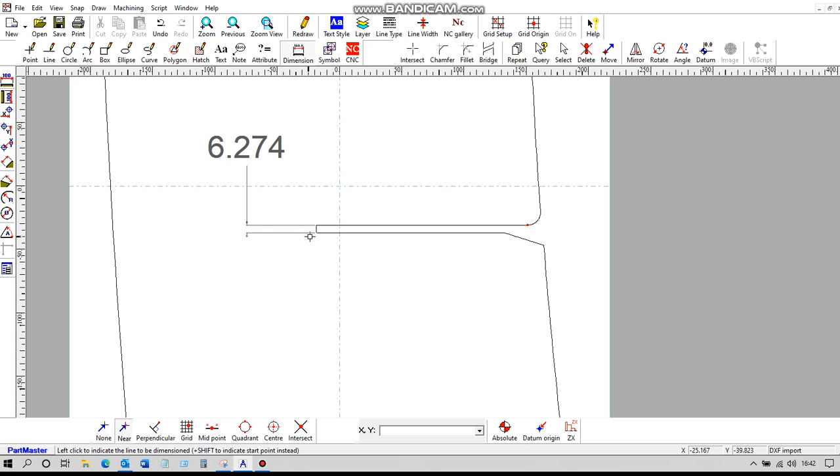Okay, now supposing we wanted to move or otherwise modify this section of that cut in. So what we can do is use the move command, and if we move an area, then we can click and drag the mouse around the area that we're interested in, and then it asks us to choose a point, click a reference point. So we go into near snap and click that as the reference point, and now we can move that point somewhere else.